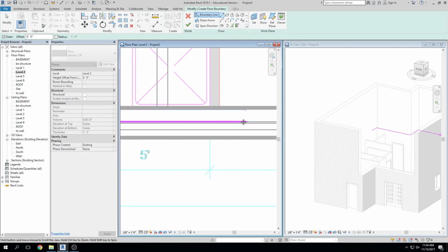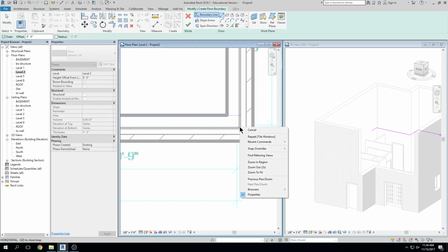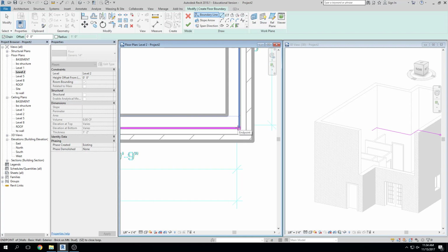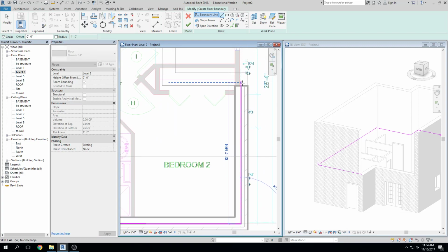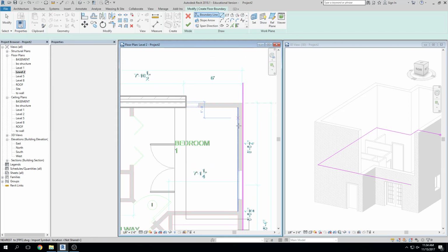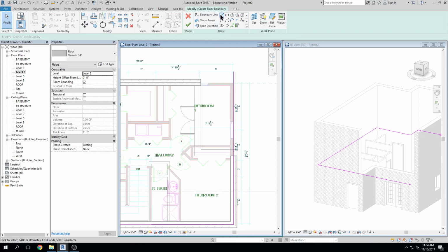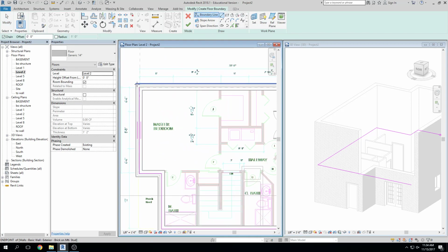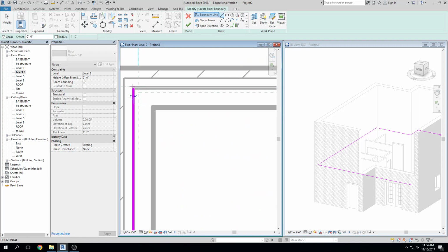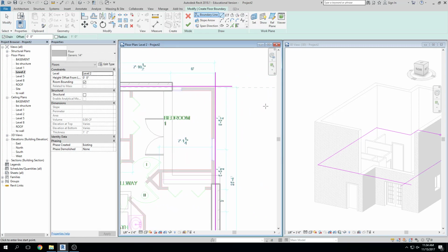And you notice over there in 3D, as I move around this, it continues. I can right click, snap override, and choose endpoint if I wanted to grab an endpoint there. Right? Continue on. And I know I'm going to have to go out here where this somewhat cantilevers out. I don't know exactly where these meet, but that's all right because I can come back up here and from the other side, grab that line and trim, TR.